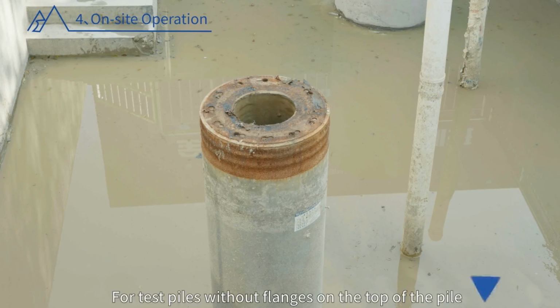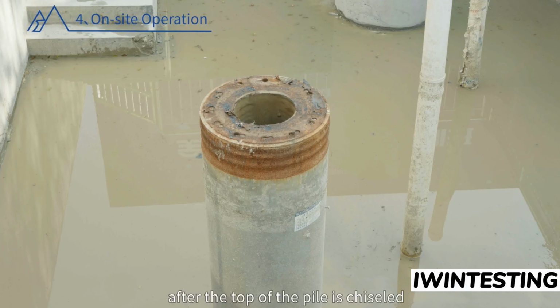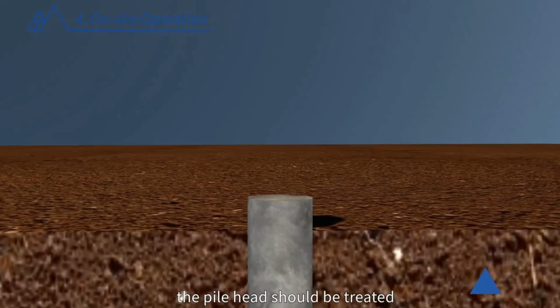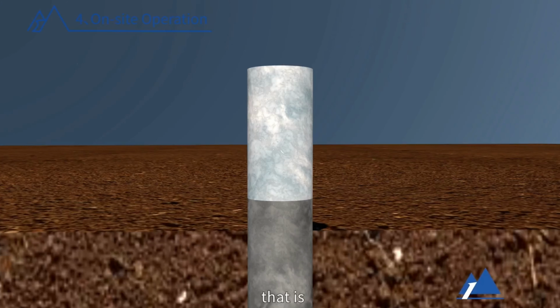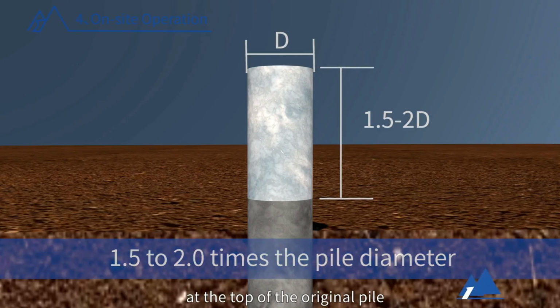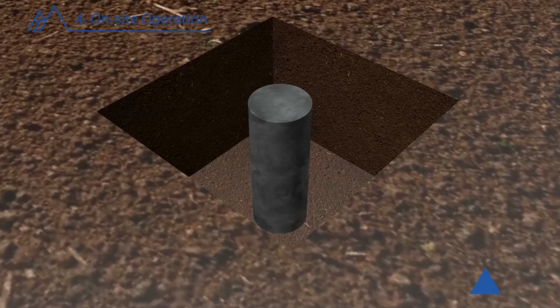For test piles without flanges on the top of the pile, the test can be carried out only after the top of the pile is chiseled. When testing cast-in-place concrete piles, the pile head should be treated by increasing the length of the pile as much as possible. That is, connecting a pile section with a length of 1.5 to 2.0 times the pile diameter at the top of the original pile, which can greatly improve the quality of the collected data.